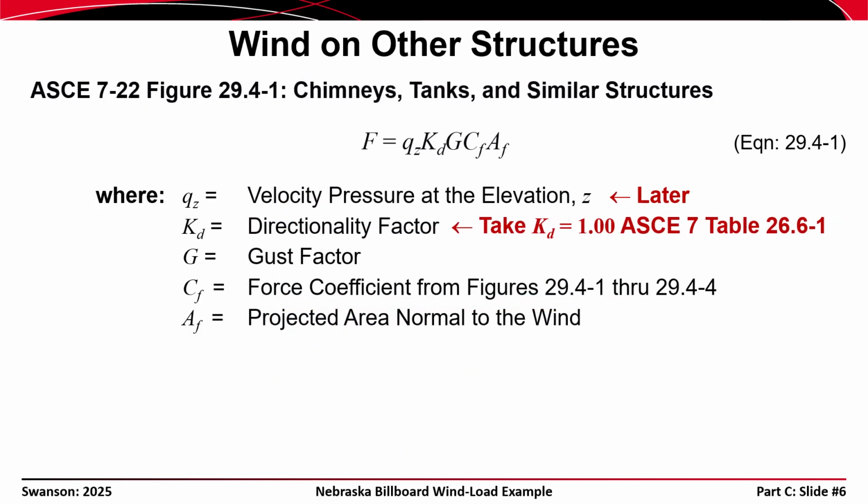Next is the gust factor G, and we'll take this value as a given value of 1.0945. The calculation of the gust factor is complex and beyond the scope of this example. You can refer to Part 2 of this example for some more background on this.